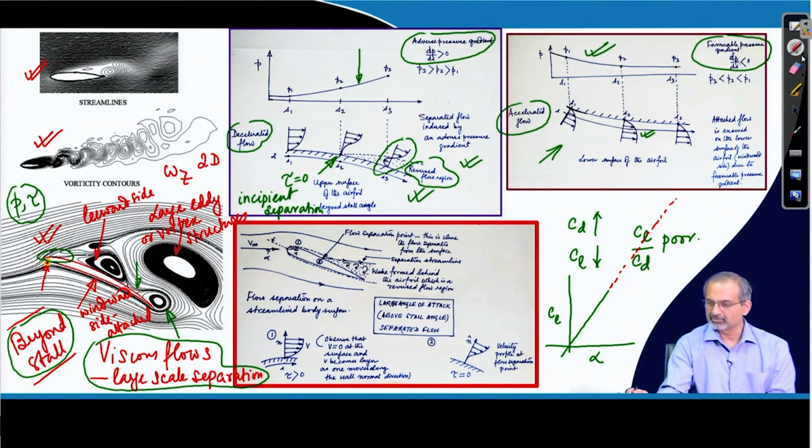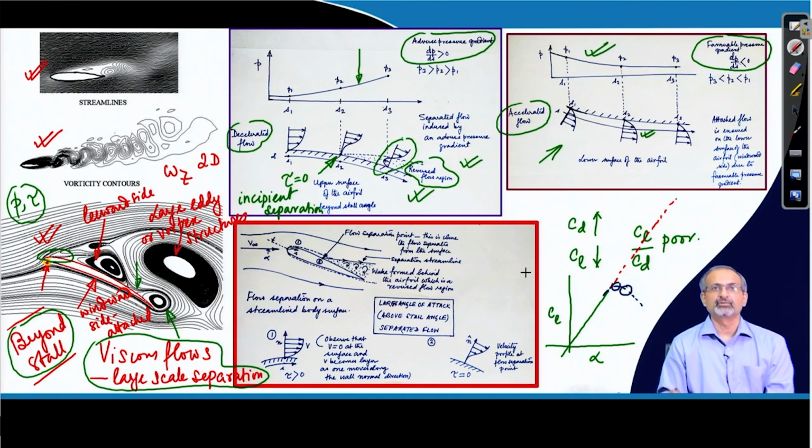So, the Navier-Stokes solution that you see over here predicts a stall, it droops down, and you are probably looking at the flow somewhere here or maybe here, where it has already stalled and you have moved into the post-stall region, and only Navier-Stokes equations can handle that, not even boundary layer equations will be able to handle it.